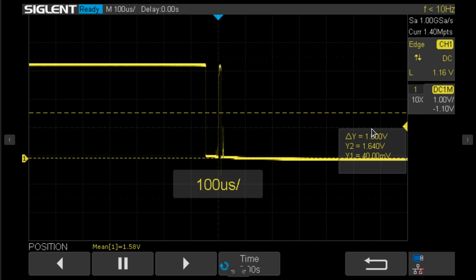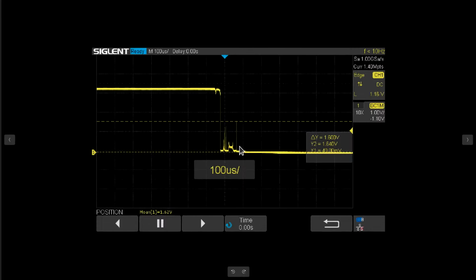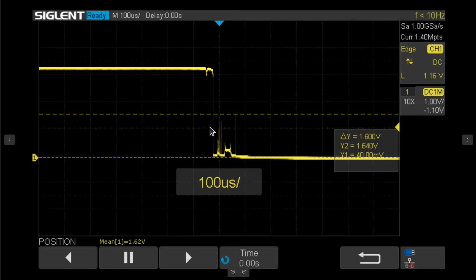This is just over 1 millisecond for the whole screen, and that'll be perfectly reasonable in terms of how much time I need to waste when debouncing, okay? So what do we got here? This one's got a little bit of noise on about 100 microseconds. Again, 1 millisecond is like the whole screen, so this is not a problem at all.